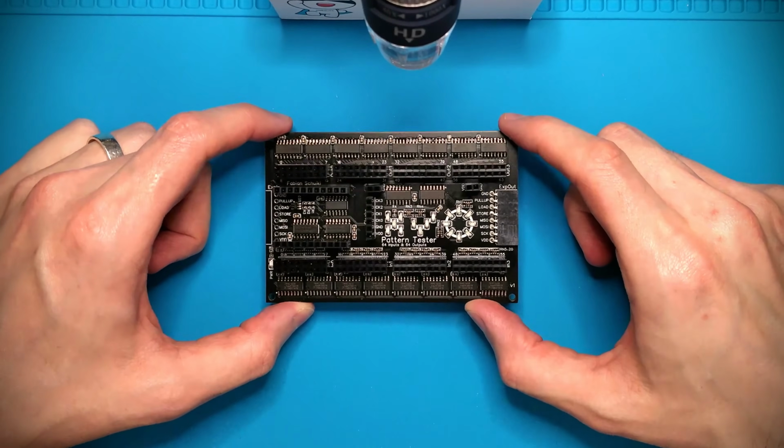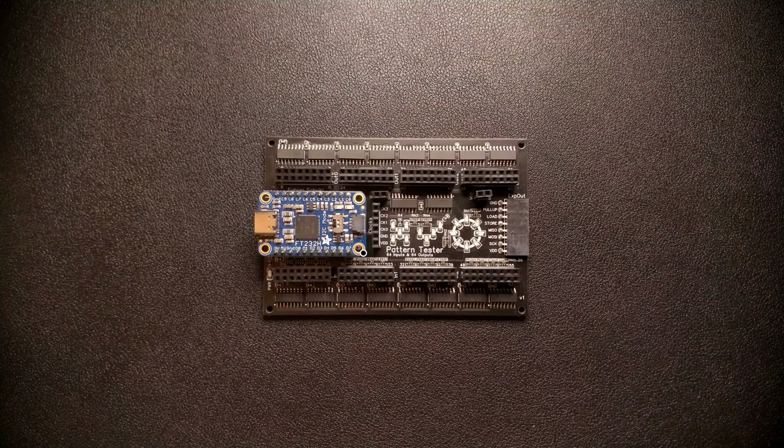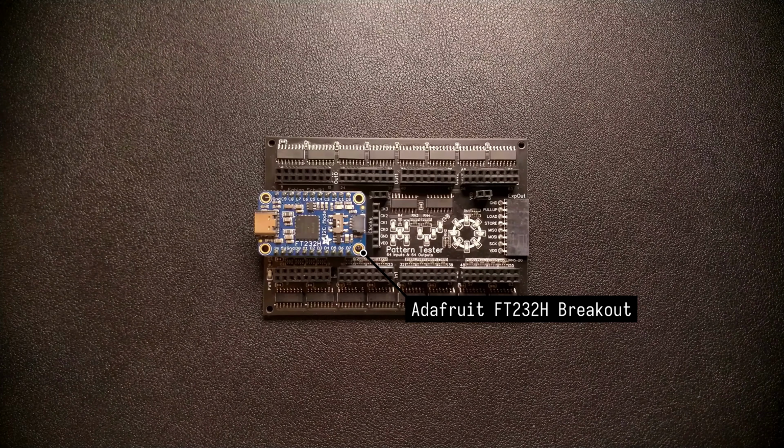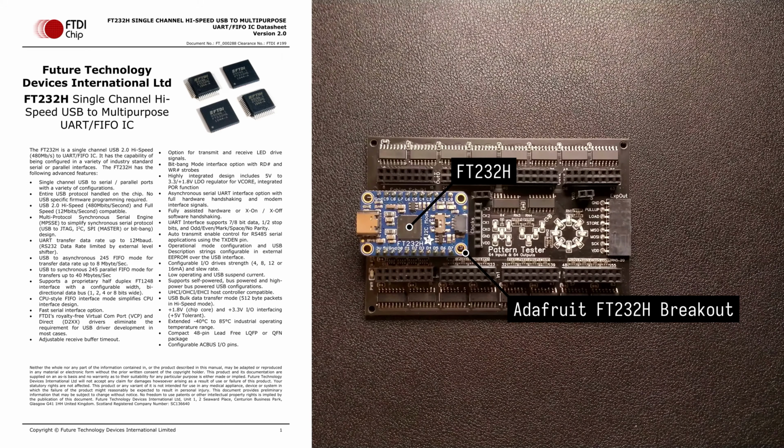Last episode, we designed and assembled this tester board here. I've since plugged in that breakout board from Adafruit, which has a FT232H chip on it. That chip translates from USB to all kinds of protocols, including the simple SPI interface that our shift registers use. Now I think it's time that we try to talk to this tester from my computer and maybe also test an actual circuit with it.